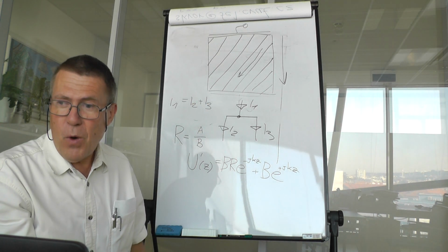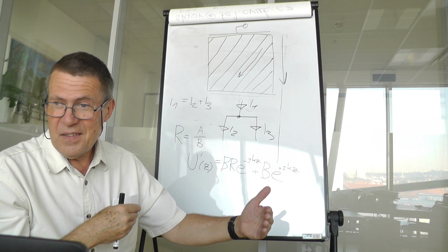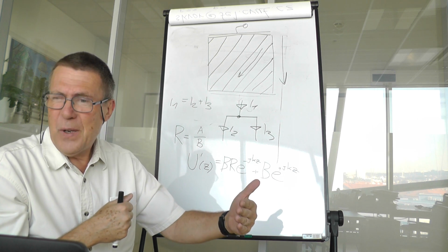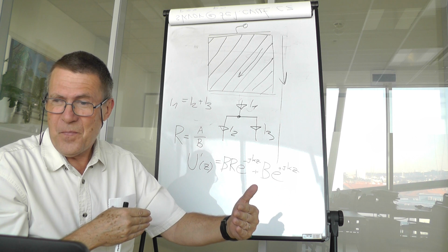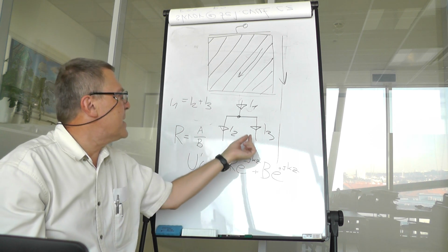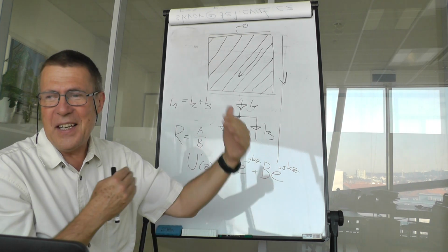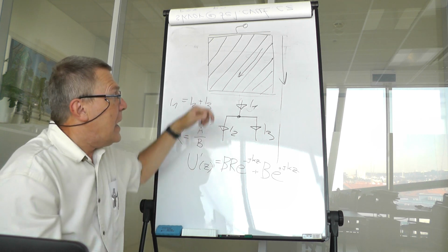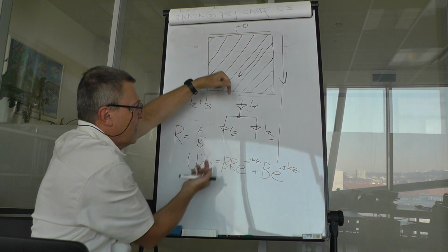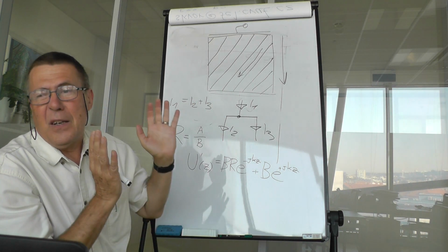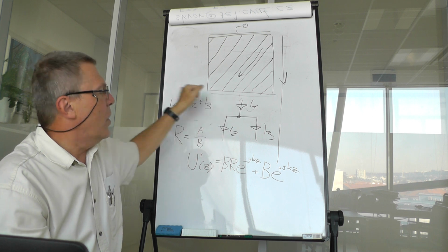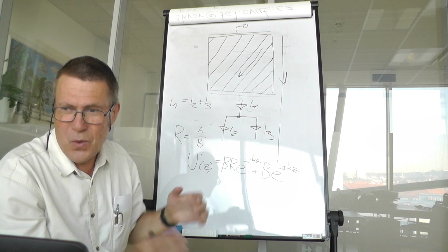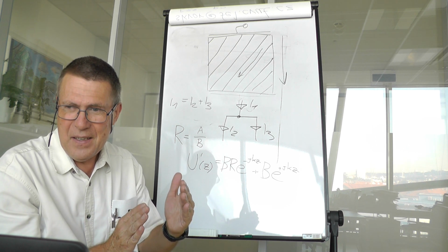Well, this is true if you observe long enough, that is, you do not have to use a high clock frequency, or if there is a lot of current. But decreasing the dimension of the conductors, decreasing currents to save power, you can get to a situation when at some time all the currents are flowing in the same direction. Well, on average, the law still holds, but at a certain moment you can violate it. You are reaching quantum effects.